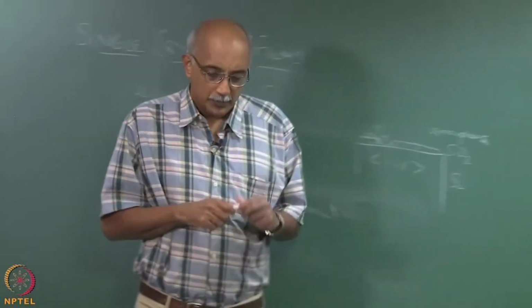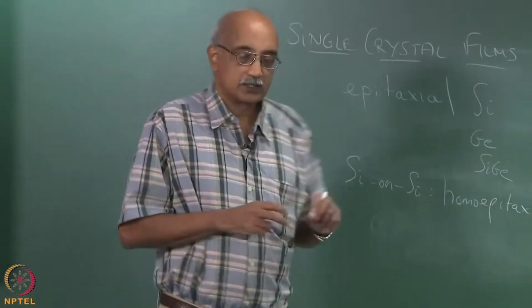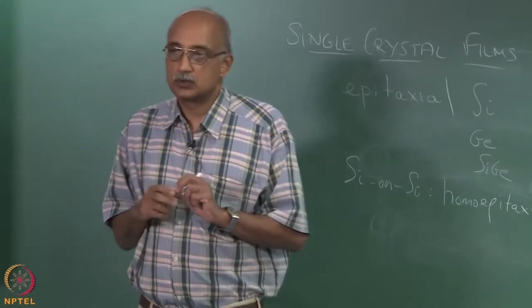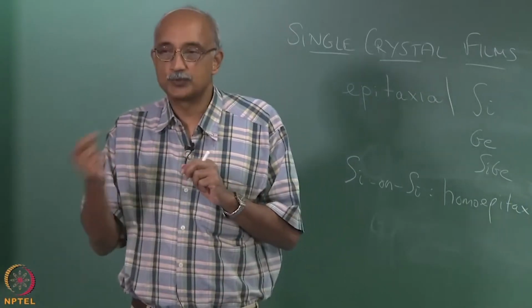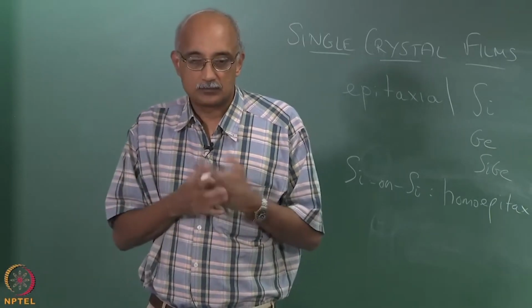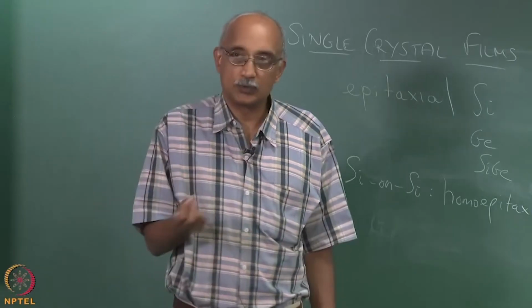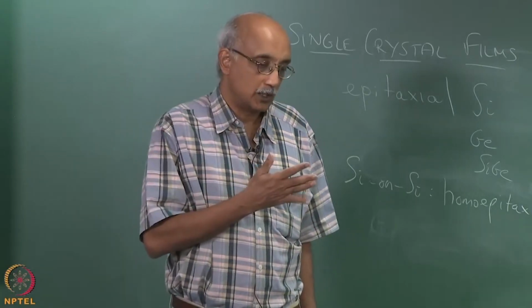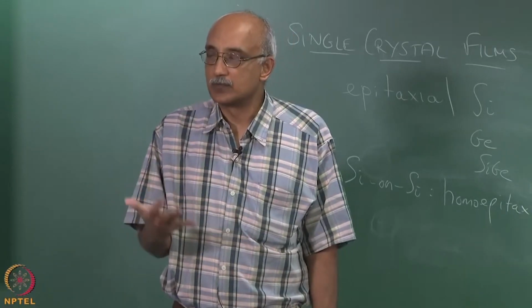Now, in an epitaxial silicon layer, one of the advantages of using CVD to form these films is that you can very easily dope the layer with other materials. For example, elements like phosphorus and boron are frequently used to lend additional properties to the CVD film.